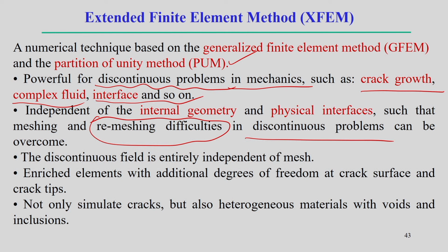In that case this crack creates some sort of discontinuity in the domain. The usual procedure to capture the discontinuity is simply remeshing the domain. That is one way to look into the evolution of a crack in a mechanics problem. But the other way, if you want to avoid creating the mesh again, is that it is not necessary to remesh the domain; rather we keep the same mesh but track the discontinuity in a different way. That is why there is a need for the extended finite element method to understand this.